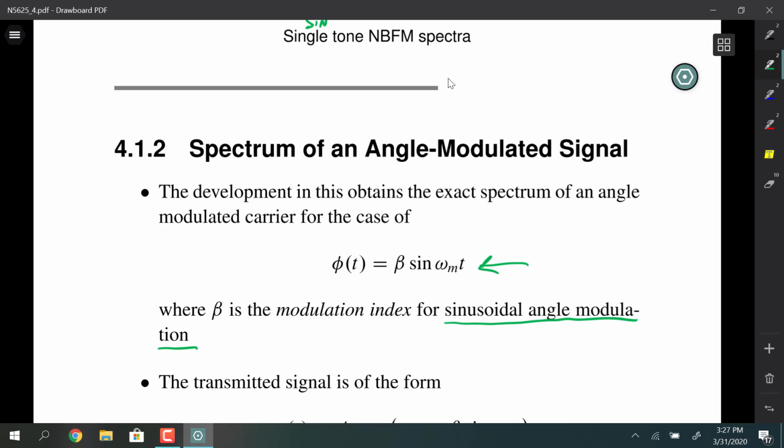So getting the spectrum, the true spectrum for an arbitrary type of message is actually no small job. It's actually very challenging, and very often you end up doing things in simulation to get there using power spectral density estimation techniques, things that we've been doing in Python for quite some time. We use that function called PSD, power spectral density estimator, on a long array of data.